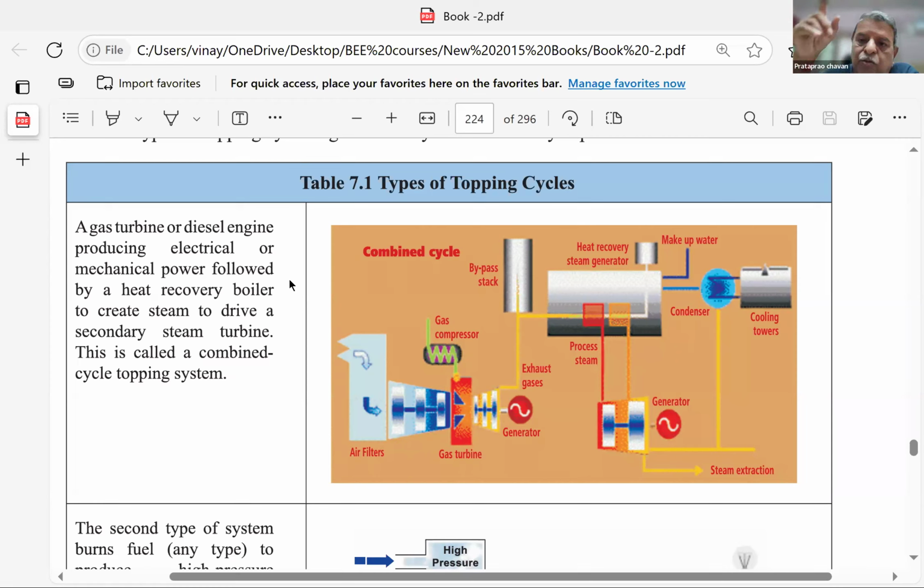So the boiler output of the steam will first go to factory and the factory process will be tapped at a pressure and temperature required for the steam turbine. That means first factory need will be attended and then the exhaust of that process will go to steam turbine and then they will generate power. So first heat and next is the power generation.